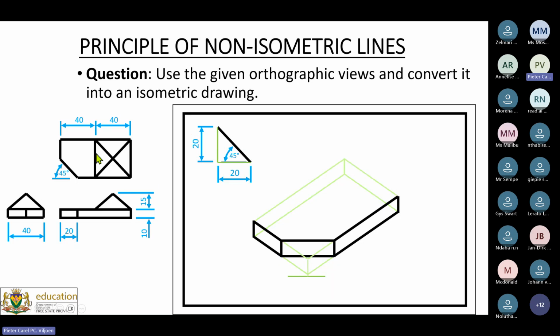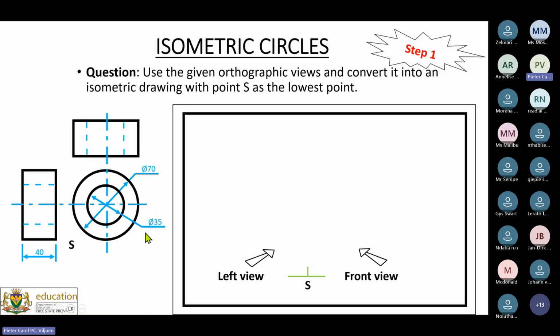Biggest possible block is required. So if you draw the biggest possible block, the learner can use this biggest possible block to raise the center point of 15 millimeters. So you can determine the center point by corner to corner, find that intersection point, go 15 upwards. You don't need to draw another auxiliary view. You can just use that tip, and then from that tip, you can simply complete the rest of it. All right, so that is isometric.